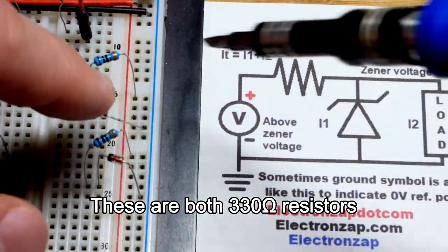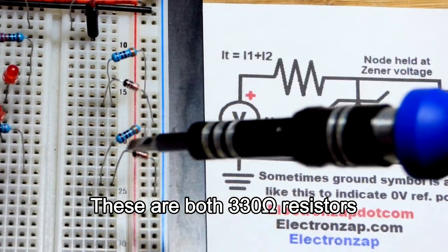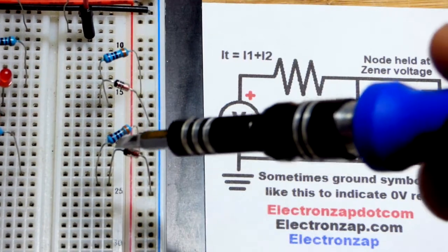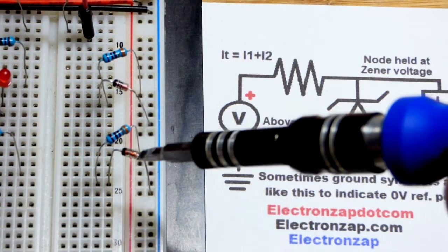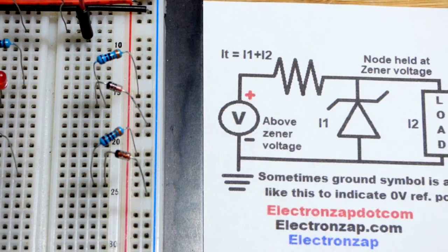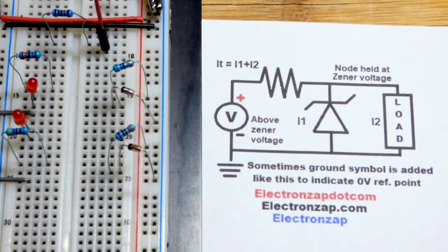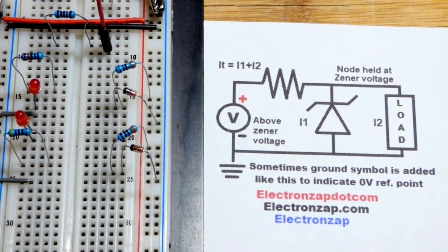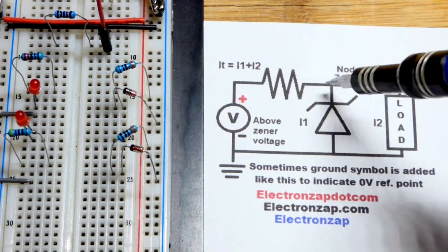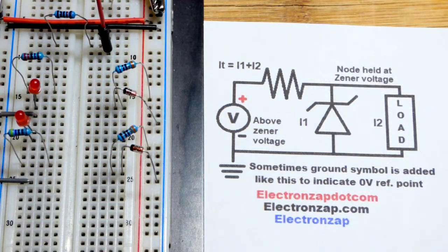There you can see the resistors to the positive side of the supply. There's a black stripe right there, might be hard to see. That's connected to the resistor, and that side with the stripe is the cathode. The anode over here without the stripe is connected to the negative rail, which is usually backwards of how you see most diodes unless you want them to block current. So that's how they are used. They're a release valve. If the voltage builds up above the zener voltage, at this point it will start conducting current as needed to hold that voltage there.